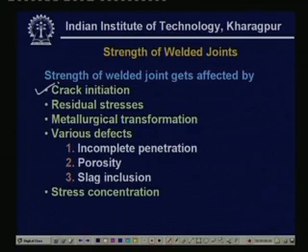We mentioned that there are a few causes of crack initiation, that may be due to solidification contractions. Then there may be cracks in the heat affected zone. Then there may be cracks due to residual stress or incomplete penetration, etc. So there are various reasons for crack initiation. Then we talked of the residual stress.